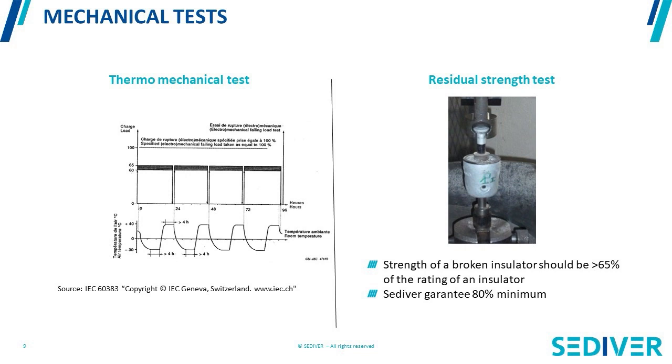Simultaneously, you apply variations of temperature, which last 96 hours as well. In IEC, temperature variations are from plus 40 to minus 30 Celsius, up and down. The Canadian climate being a little different from most other climates, the Canadian standard actually asks that you do this test with temperature variations from minus 50 to plus 50 Celsius.